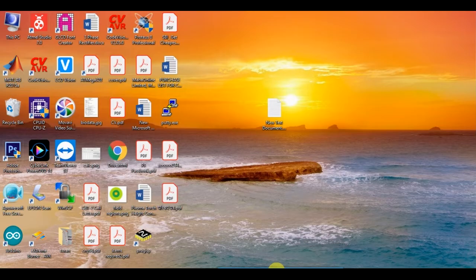I am going to design a log periodic dipole antenna using CST MICROWAVE Studio, and then I will build the actual antenna. But before that we will design this antenna in MATLAB. That is, we will use MATLAB to calculate all the parameters, values, length of elements, and other required parameters like alpha, sigma, then the total length of the structure, and so on. All these parameters will be calculated using the program developed in MATLAB.